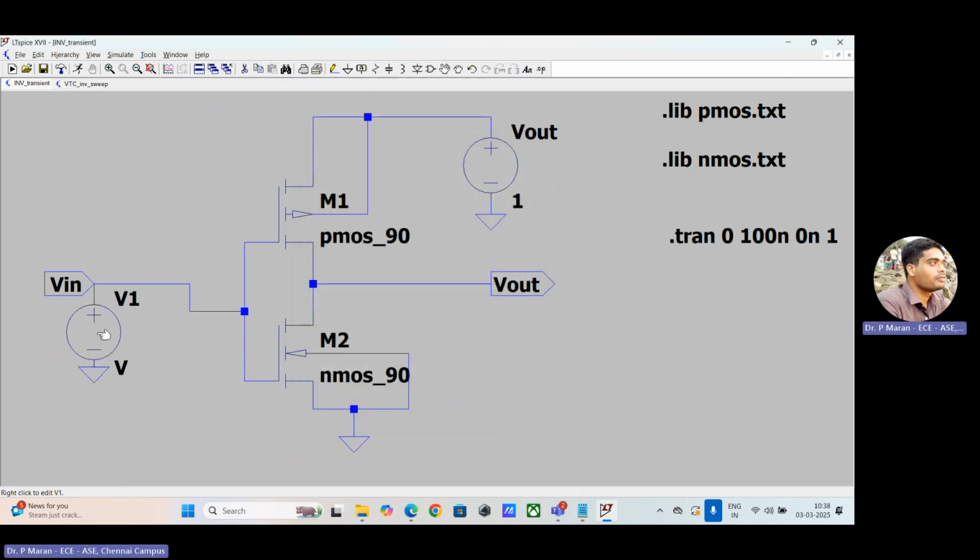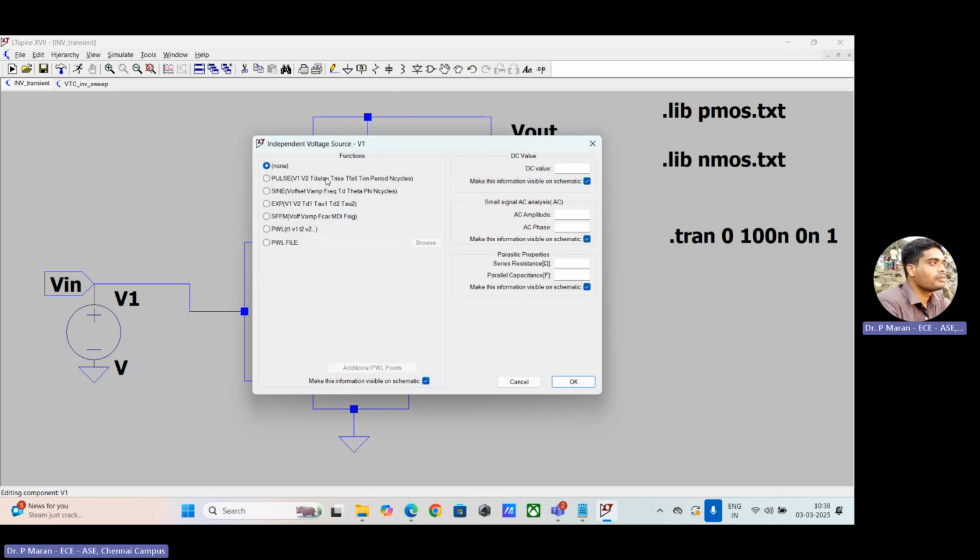Now, if you right click over there, you can just give 1 voltage or 2 voltage only. But how can you give a square wave input to this particular circuit now? In the last option, advanced is there. Click over the advanced, select pulse type of signal. Initial voltage, I will give as 0 volt. V on voltage is 1 volt. And time delay, I don't want any delay, so let me give it as 0 nanoseconds.